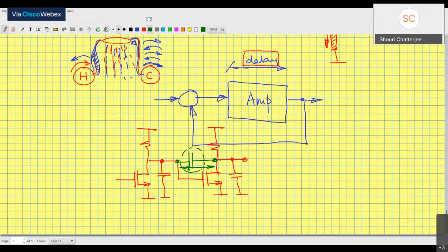If your output is going to clip because of the swing limits, then you are applying a signal that is too large, so make it smaller. I hope that answers your question. Mathematically speaking, the answer is infinitesimally small. But practically speaking, you can make sure that the swing limits are okay, and then you can deal with it.